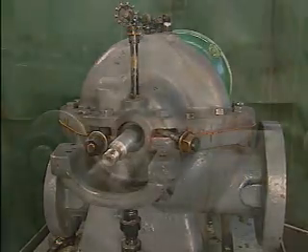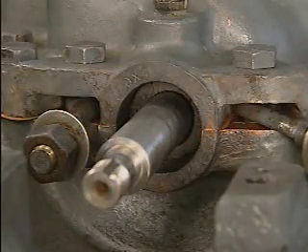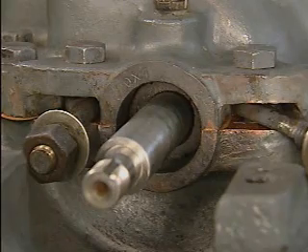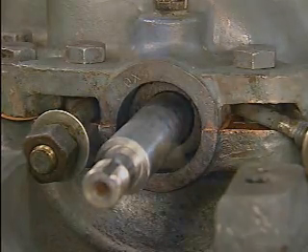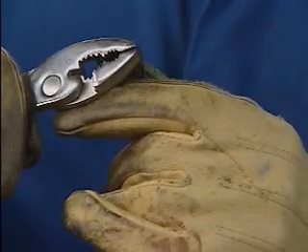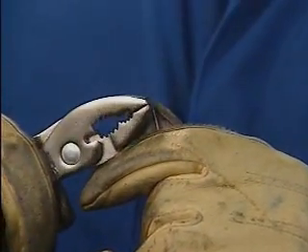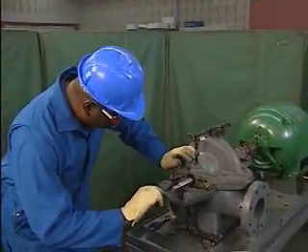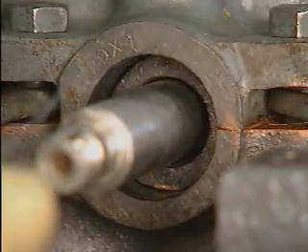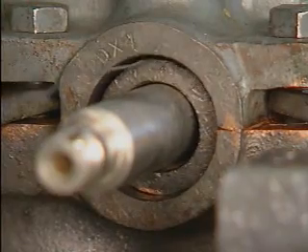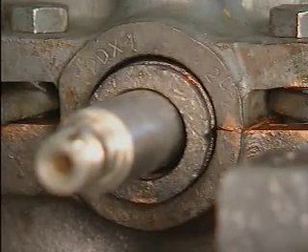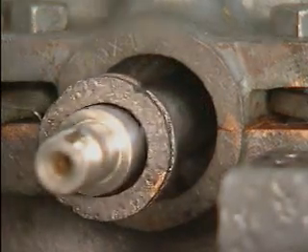On this pump, a lantern ring is positioned between two of the rings of packing. In order to remove the remaining rings of packing, the lantern ring must be removed first. To do this, the mechanic takes a short piece of stiff wire and bends one end to form a small hook. He inserts the wire into the stuffing box between the lantern ring and the wall of the stuffing box. He then hooks the wire onto the edge of the lantern ring and carefully slides it out of the stuffing